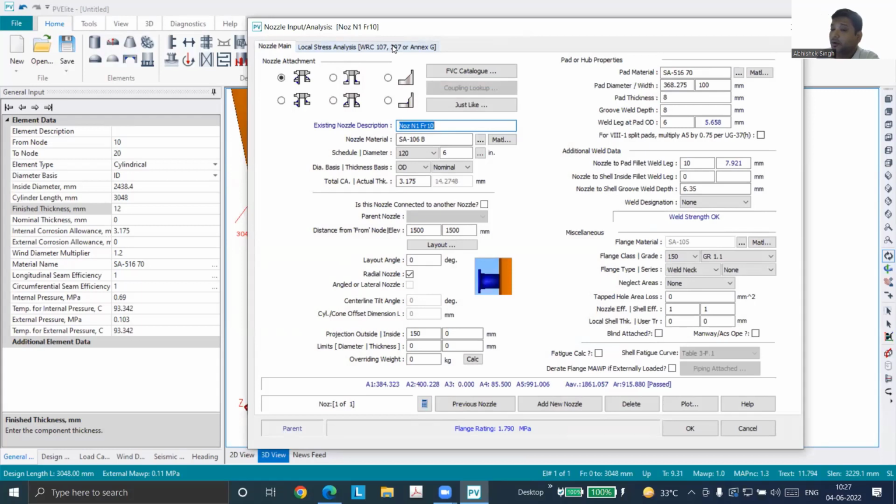How are the stresses coming because of the pad? How is this related to pad dimensions? See, the pad is also providing stiffening, right? The thickness till that location is more, where your pad is providing stability to that load. That factor is also considered in WRC. So the WRC considers pad dimension as well as shell dimension.